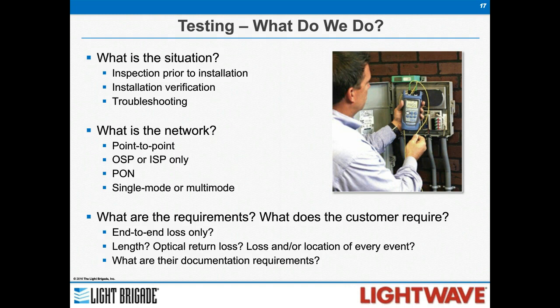And then you need to consider what network you're testing. Is it point-to-point? Is it outside plant or inside plant? Is it PON, passive optical network, so it may be point to multi-point? Are you testing single mode or multi-mode? And then what do you need to report, whether it's for yourself or for a customer? Are they requiring loss only? Do you need return loss? Do you need to verify length? What are the requirements? All those things will play into what equipment you need to put in your technician's hands to get the job done right.